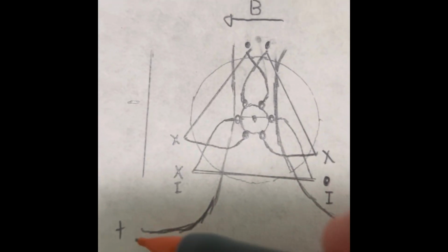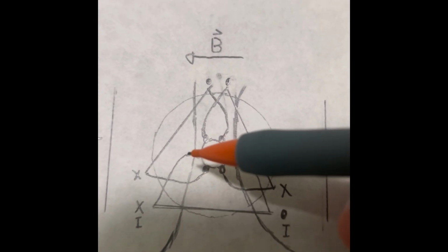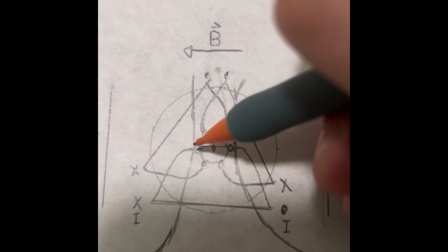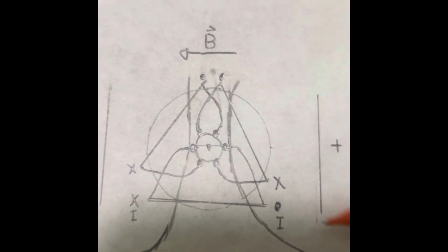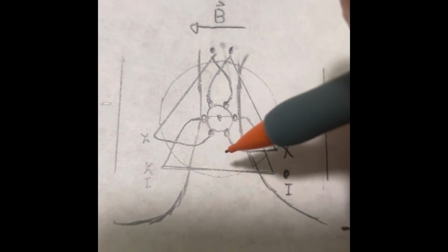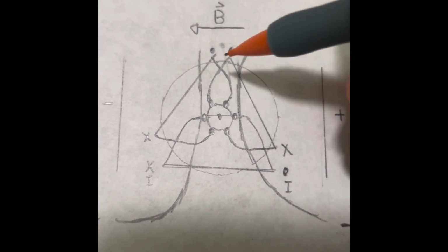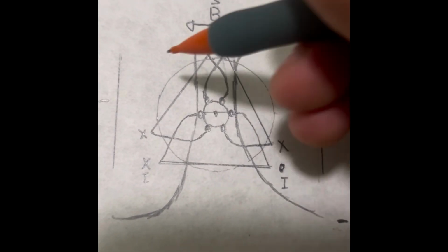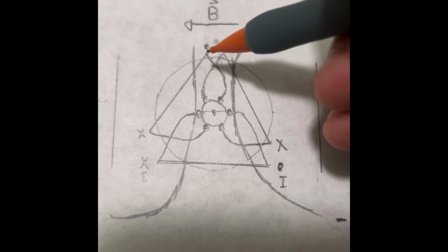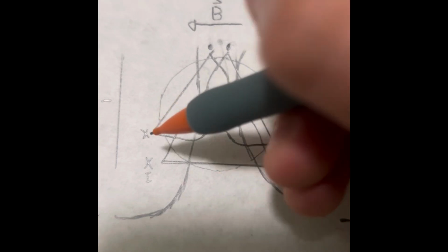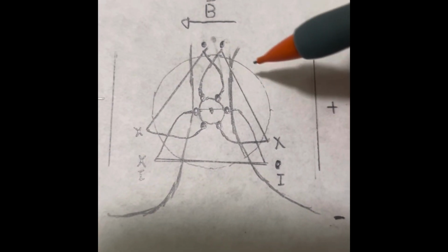So as you can see, positive will come through here, negative there. This is the brush. The brush is just going to be one wire. So when it's connected to this one, it'll be going in this way and out this way. Negative side of the battery's over here, positive's over there. So it should rotate this way, at least enough to point this one up to the side there. Now this one actually has to have the opposite current. So it's going to be in that way, out that way, and it's going to rotate this way.